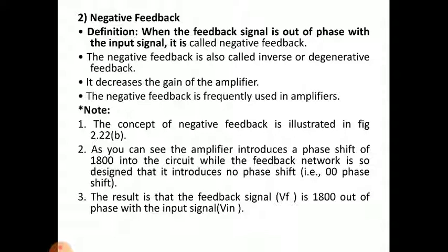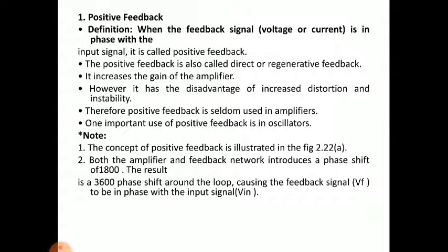So negative feedback is frequently used in amplifiers. Of course it decreases the gain, but we still use it in amplifiers because of its stability and less distortion compared to positive feedback. The concept of negative feedback is illustrated in figure 2.22b. Already we have seen it.